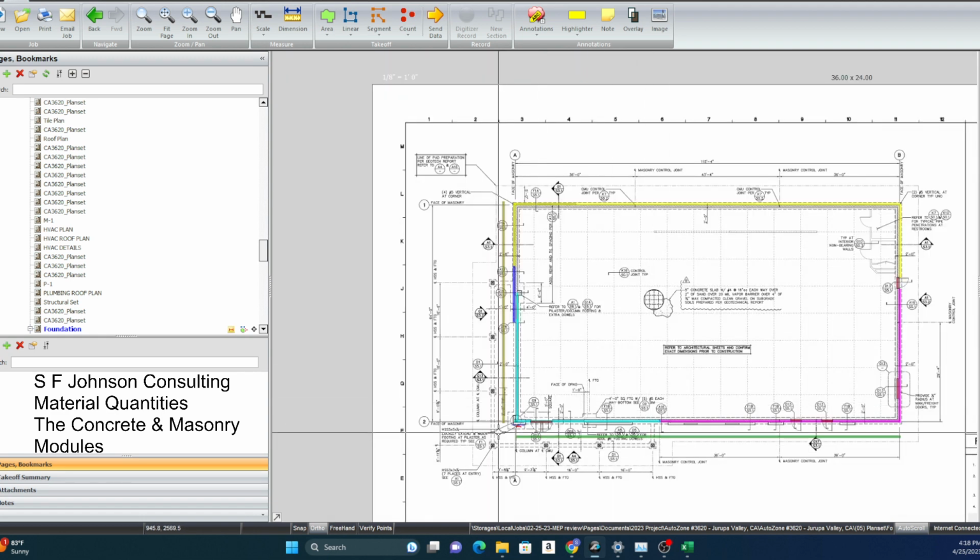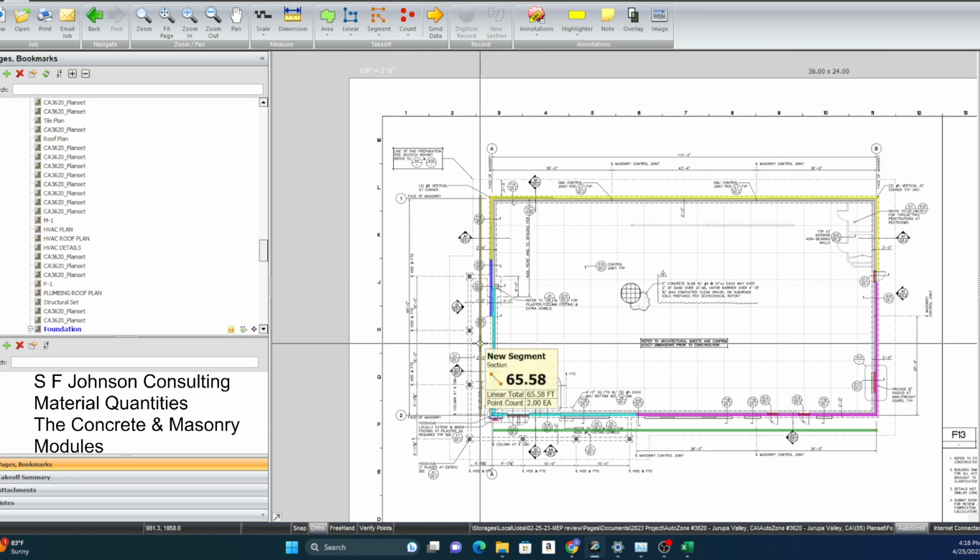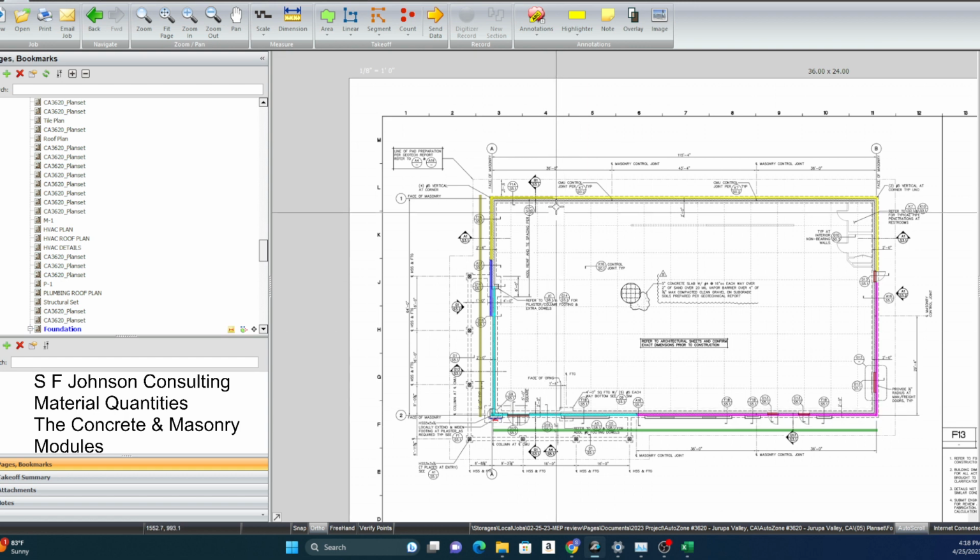But the number of placements is change this many feet, 116 feet times 12, change it into inches. That changes it into inches. And then you divide by 16. That tells you how many times you have to place it. And then that many times that length times 66 feet is the rebar just for that distance.